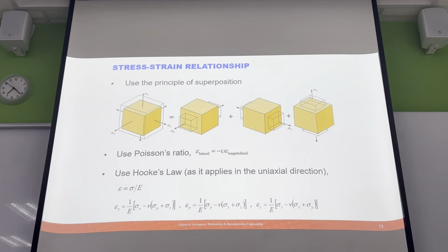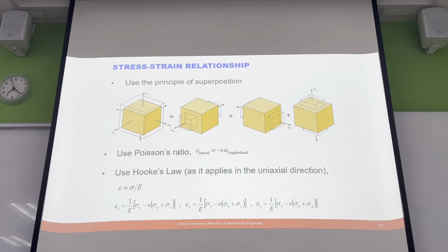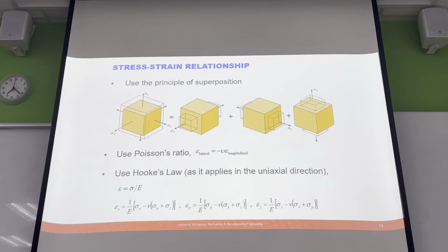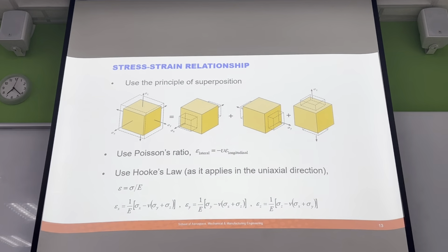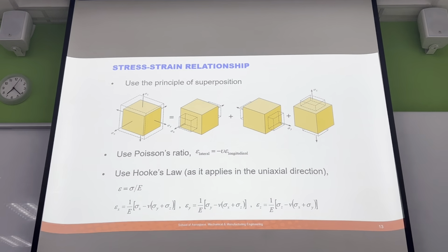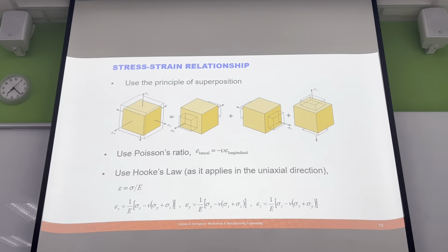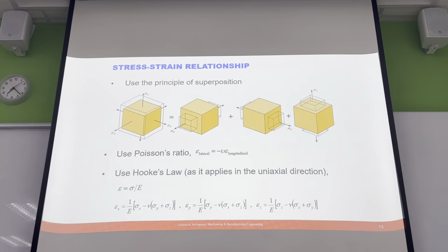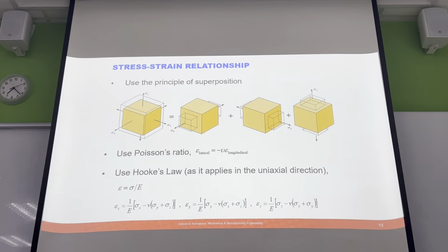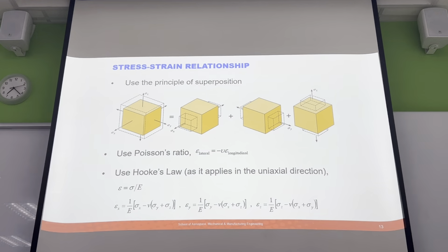But if we assume that it is plane strain, which means that all of the strain occurs in the xy plane and there's no strain in the z direction, then that means this has to be 0, and therefore, if we have strain in the x and y, the only way that this can be 0 is if we have some amount of stress in the z direction.